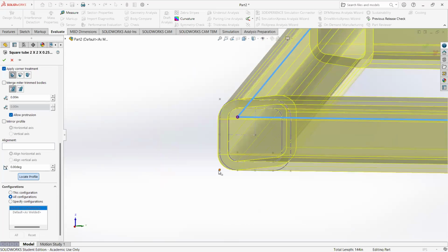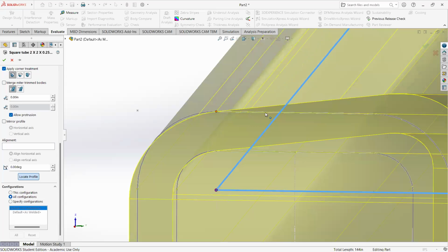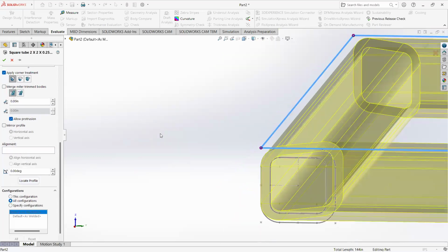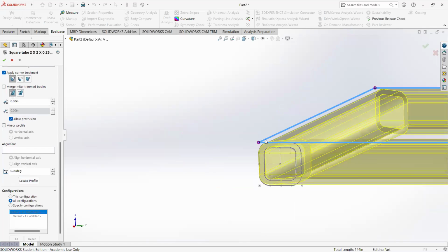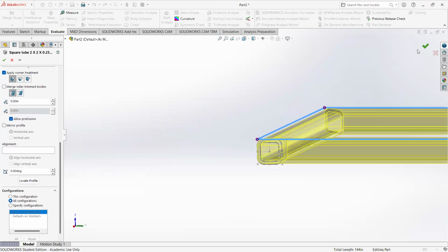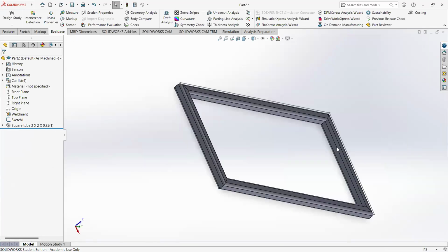And if I click any of these outer dots, this sort of star shape, it means that when this sketch was created by the folks at SolidWorks, these are just points in space. And I'm sure if we look at the sketch details, it's constrained, so they're in line with the top edge and the side edge of the tube. But if we select one of those now, I'm completely inside my 48 inches. So if I accept that now and go back to the top view, I'm completely inside that 48.